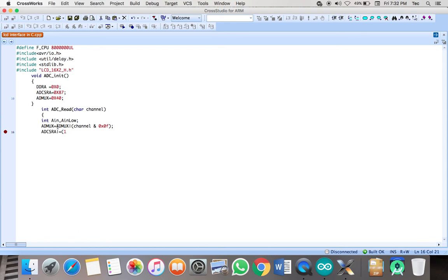So you are starting the conversion, because when you enable the ADSC bit of the ADCSRA register, it means that you are starting the conversion now. When you enable that, the conversion has started, and then you call a while function.